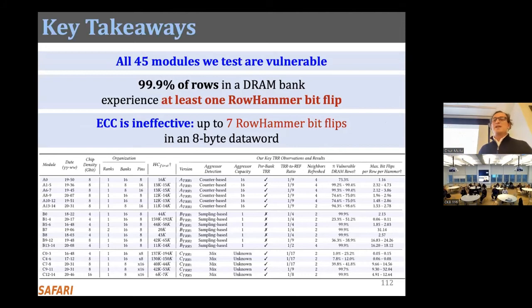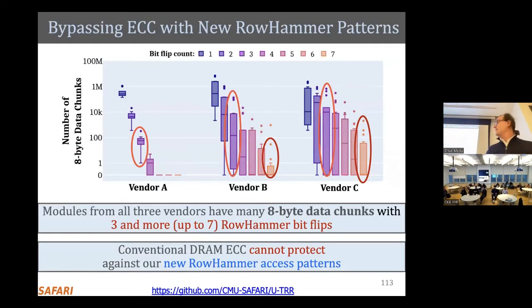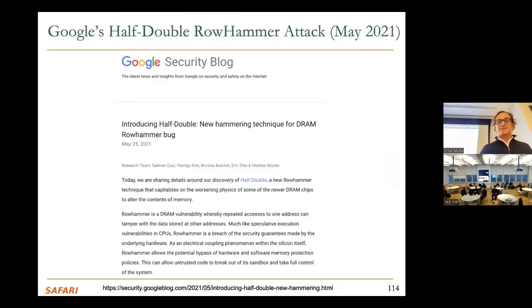Okay, so basically, you could reverse engineer essentially all DRAM chips over here. I'm not going to go through this in detail. There are a lot of interesting things, but essentially the underlying solutions at the time were perfect or imperfect implementations of sampling-based mechanisms like PARA perhaps, and counter-based access mechanisms. Going forward, I think we need to do better, and we also show that ECC doesn't work unless you go to very high protection levels.